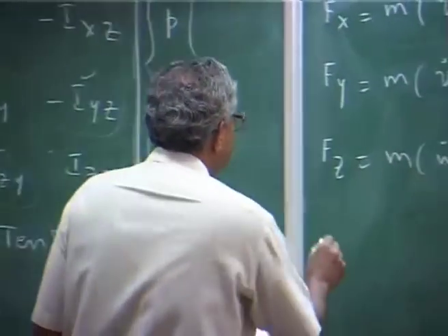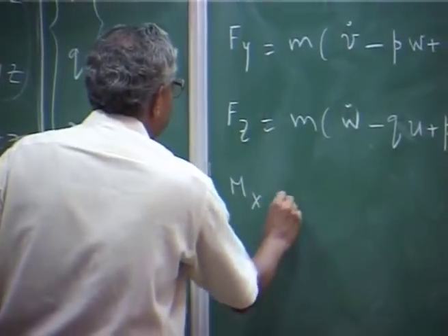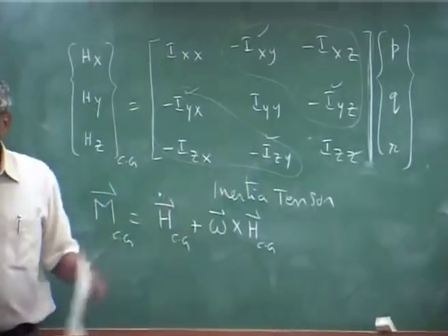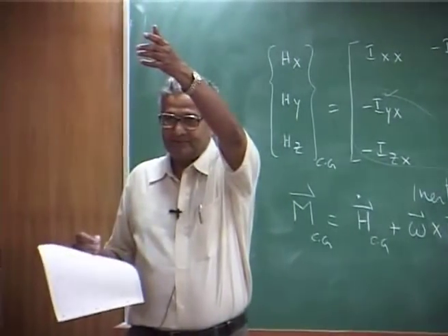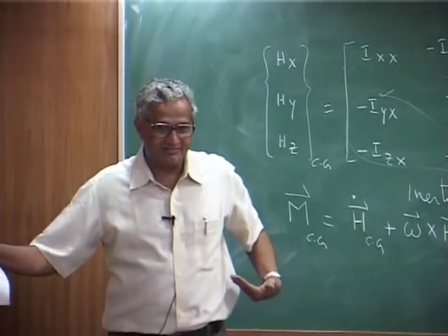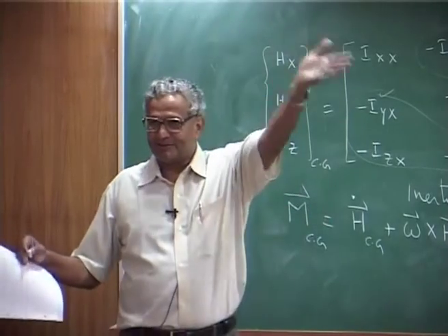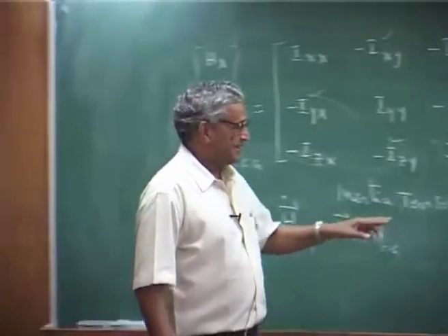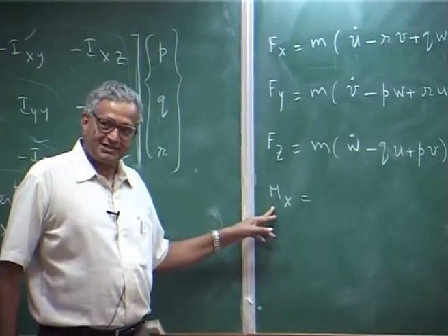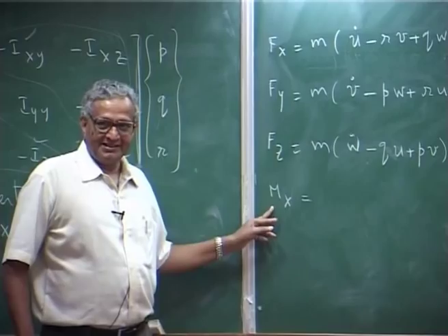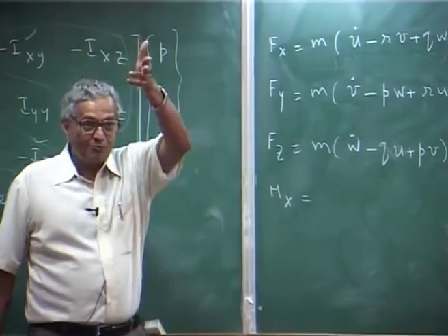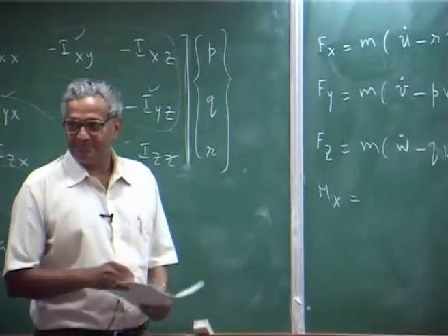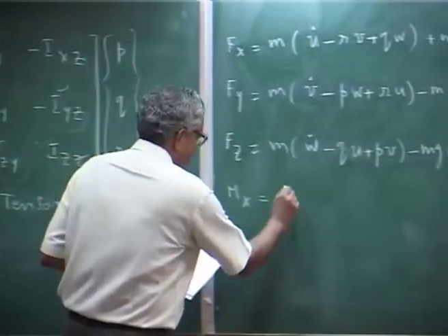But you say that it is all right, let me make that assumption, because then I can write it in a smaller form. So, I will have Mx, the moment of all the loads, that is the rotor loads, tail rotor, horizontal surface, every aerodynamic load, inertia, everything, transferred to the CG. That is along the x direction, the Mx. That is why we get Cmx, Cmy, Cmz, all those things, the rotor loads transferred to the fuselage center of mass.